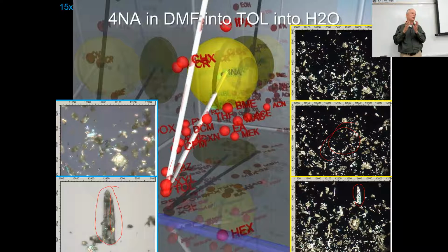This explains certain situations because surfaces have Hansen solubility parameters too. I've put this molecule in toluene, a solvent it does not like. And what else is in the container? A Teflon stir bar, and a glass surface. Now, this molecule is polar. It's going to like the glass. It's not going to like the Teflon. But what if I had a stainless steel tank, but I used a glass-coated impeller versus a Teflon impeller? The glass and the Teflon impeller may produce different results, and yet you've got the same temperature, same pressure, same volume, same stir rate.